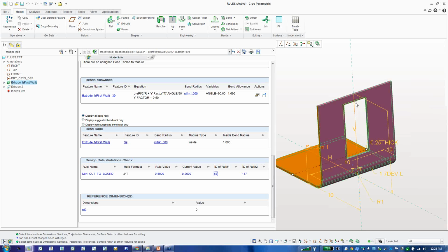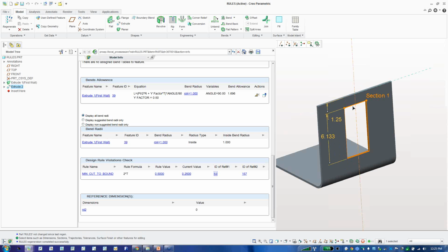So one of the things I can do is I can hover over the sketches, right? And so you get that different arrowhead. You see the arrowhead looks like this now with the cross on it, and if I come over and hover over it, it turns into an arrowhead without a tail. That means I'm right on top of a sketch, and if I select down with my left mouse button, I can actually drag and dynamically regenerate that. All right, and so once I want to accept that, I just double-click out here.